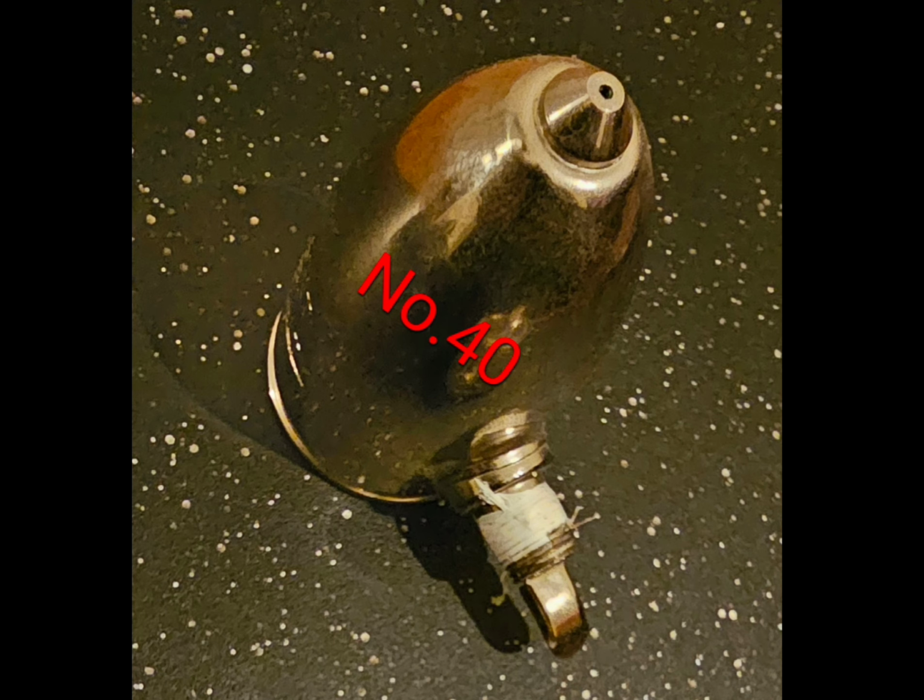And it looks ugly as hell because then they put this excessively large pitch on the radiator, so one half of the radiator is literally dangling in the air. It looks ridiculous, but anyhow, that's beyond the point. But that's the only place you will find 3/4 inches. The standard size you would find on an inlet for a one pipe steam system on a cast iron radiator, or even a steel convector or whatever, is going to be 1 inch to 1.25 inches, all the way up to 2 inches.